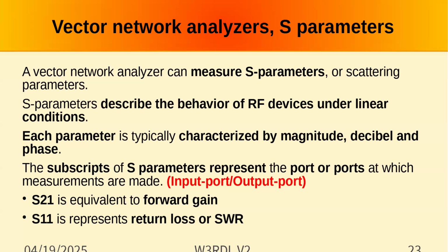One thing again, you just said input, output, okay? Input on 1, output on 1. How can you have the input and output on the same signal? Because I have a transmitter and a receiver connected to that port internal to the device. Transmitting down the line and measuring what's coming back, the same line into the same port, and I'm analyzing. That's what your Rig Expert does too. It sends out a signal, it looks at what's coming back on the same port. It's doing an S11.